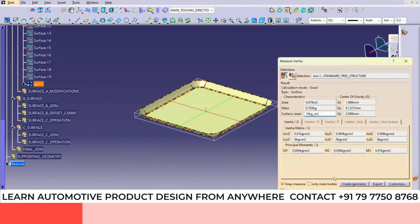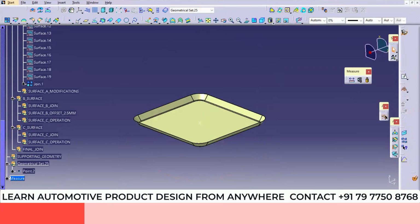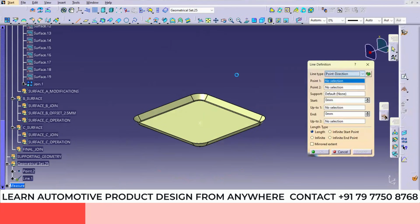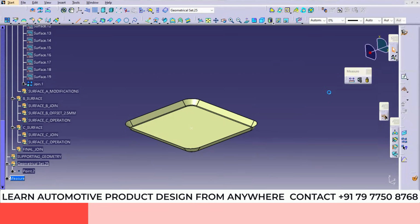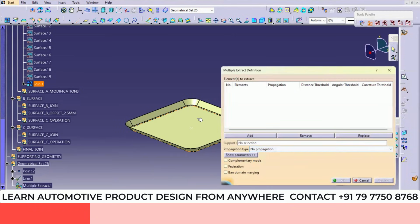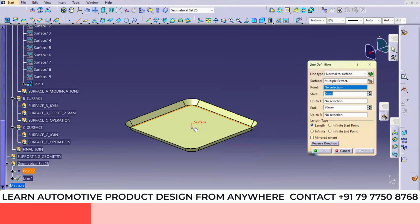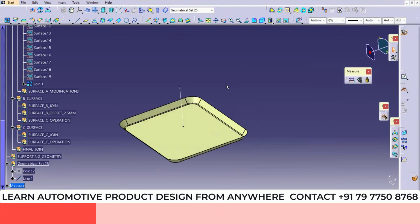Okay, create geometry, CG point, click OK, click OK. Okay, then we'll create a line here, point and direction. Okay, the point is this and the direction will be, oh sorry, normal to surface we want, right? So for the line I'll take normal to surface, right click, multi extraction. This is a big patch, I'll select, click OK and select the point. Okay, so here I'll add the value. Okay, so this is my tooling direction.